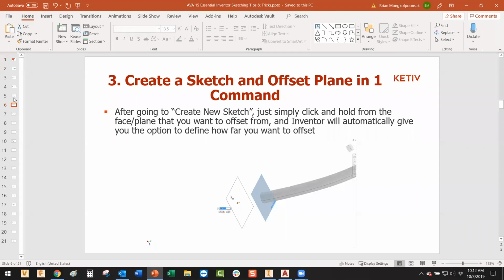Brian, I know you went over zoom extents to be able to zoom. Another really cool one that I use all the time is, instead of hitting that fork key, I just hit the center mouse button twice. If your mouse scroll wheel is also a button, if you hit that twice consecutively, super fast, double click it, it should zoom extents. So Brian, if you want to show that real quick too.